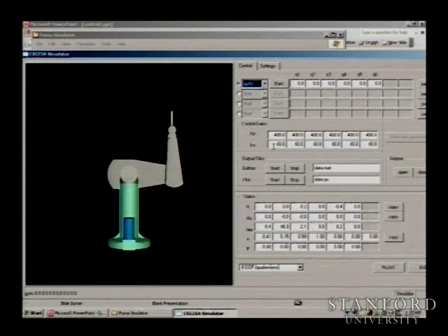These are the gains we set for the robot. But in fact, this is controlled also with dynamics, so we will get to this a little later. But if we want to see the control without dynamics, we take this non-dynamic joint control, so this one. So let's float it a little bit. Actually, I can exert a little force from outside and see if it can move. It's really solid. Well, you cannot move it too much. So let's reduce the gain here.